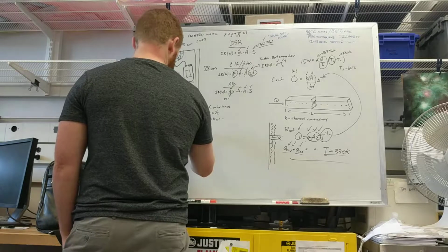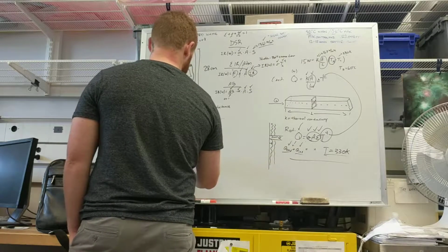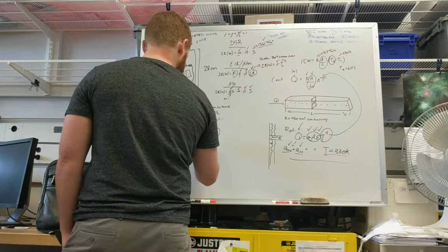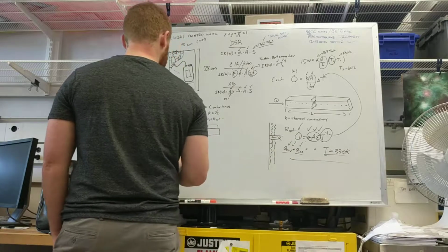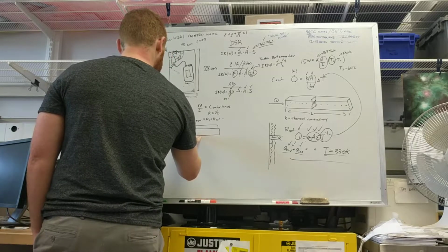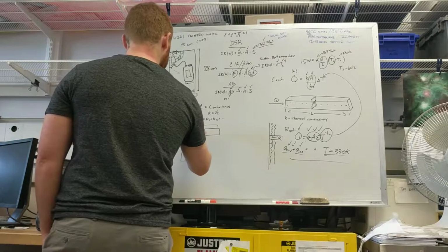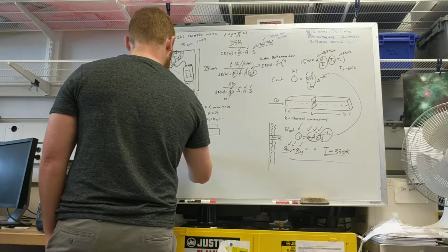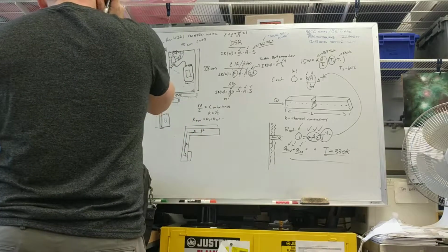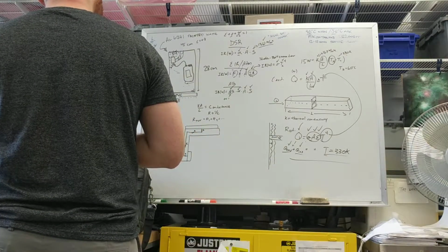So when you're dealing with a bar like this, and you have some source that's here, and you're dissipating to something up here, you would compute the A over L, so you'd have a resistor here to get to there, and then you come up to here, and I'll treat that as one. You do an A over L for that, so you find the resistance there. Then you'd have a resistor there, and then a resistor to there. So you could do it that way.